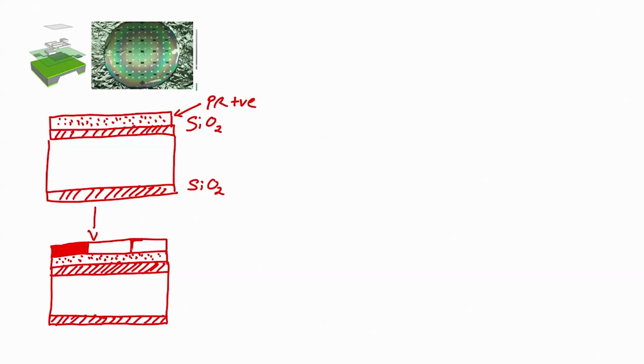That means we will create a window by etching silicon dioxide, because finally we want to create a diaphragm and then fabricate the remaining structure of the sensor. So, this is my mask.